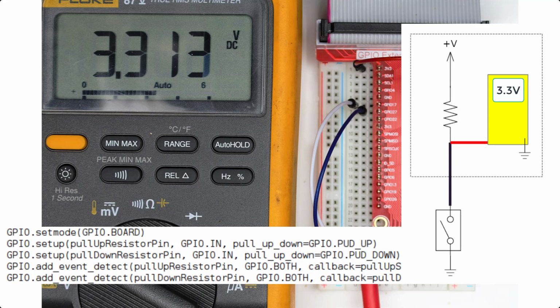At the very top I have a plus V that indicates that this is a pull-up resistor. The plus V could be 3.3 volts, 5 volts. If it was on a different system, it could be even higher. So in our case, we're running 3.3 volts. Below that is a fixed resistor. That fixed resistor is used to drop the voltage when the connection is made to ground.